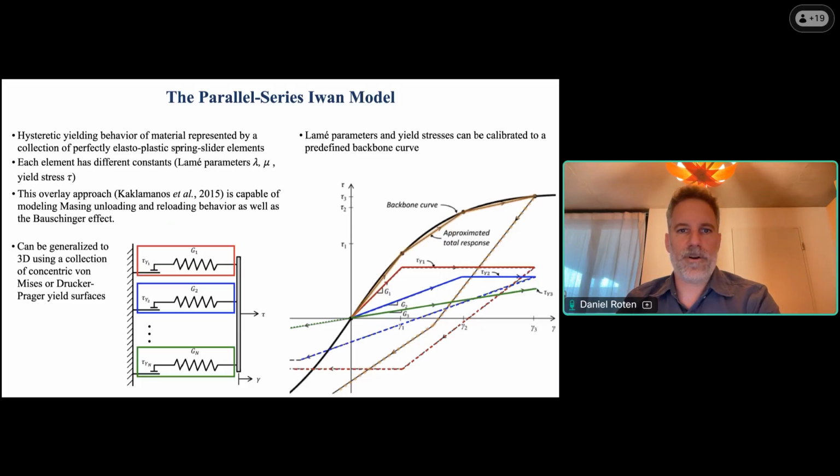So the next improvement we worked on was a multi-surface nonlinear model. The J2 or Drucker-Prager plasticity I mentioned before is very simple. In that case, during loading, the stress-strain relationship stays linear until you reach the yield stress, at which point it becomes flat. This is not really the behavior that you observe, especially from soft soils during lab measurements, because those tests show a more gradual reduction of the shear strength until the material yields completely. And this is actually more tricky to capture numerically.